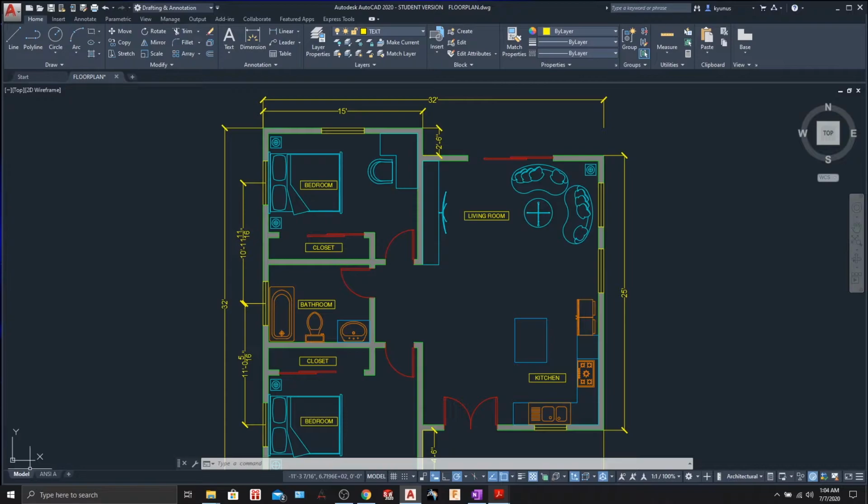At the bottom you see an axis system, which is the UCS, and this is our viewport control, so we know what our view is, which is the top view with 2D wireframe, right? This is our command center, which already says type a command. So if you type, let's say, line, it wants you to specify a line, right?